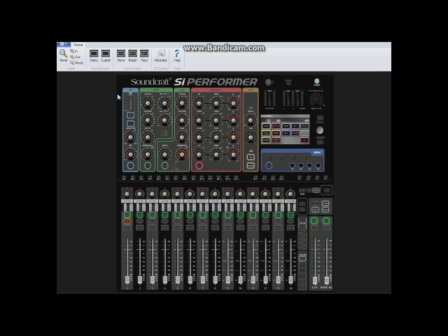So in this strip right here, we have the meter section. In the meter section, when you have a single mono microphone coming in, the left side will be the meter, and there's a green light up through here, yellow light here, red light there. Certainly you want to keep in the green, and maybe you're just taking the yellow occasionally. If you're too high up, you can neutralize or center that input signal coming into the channel by the gain trim here, adjusting that up and down.